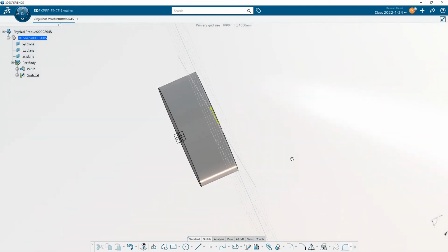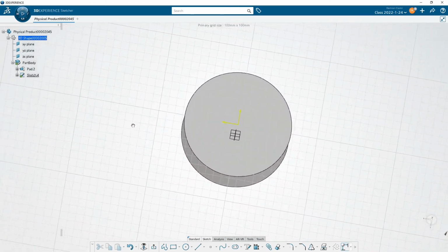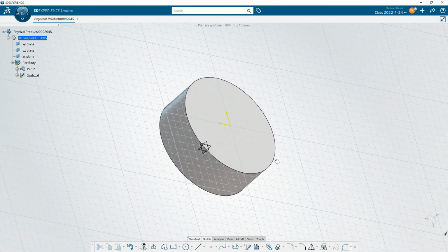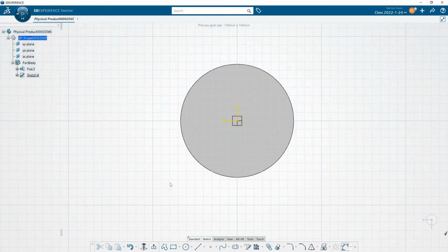And if you notice, when I turn this, you can see that that sketch plane is on the top of this part. Now I've turned it, and if, by the way, that bothers you, well, I can always go to some of my different icons down here to help me out. So this one here that's got the plane with the little eyeball looking at it, this is normal view. In CAD software and in CGI software like Blender, if you see these words called normal, they mean perpendicular, okay? So it's not normal like, would you just please be normal? It's, would we look at this in a perpendicular way? So if I hit this, it's going to flatten the plane out, you see?